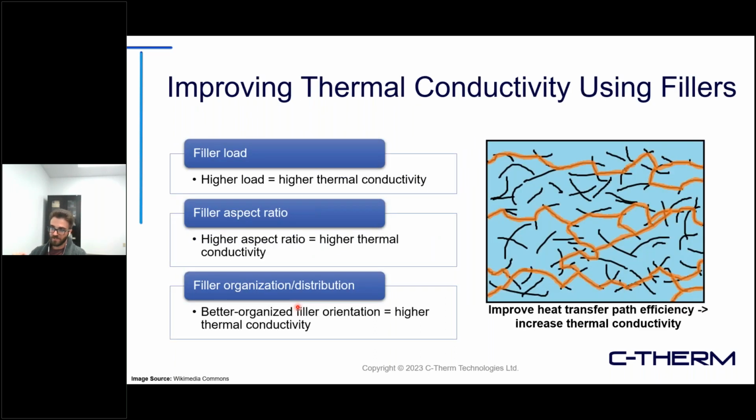And I would say, without a doubt, one of the most common ways of doing so is introducing filler into your sample. Fillers are really what are going to do the heavy lifting with respect to heat transfer. So whether you're developing samples by just simply adding more filler, generally speaking, a higher filler load should result in a higher net thermal conductivity, better heat dissipation. With a certain caveat there, I have an example to kind of highlight where this may not always be the